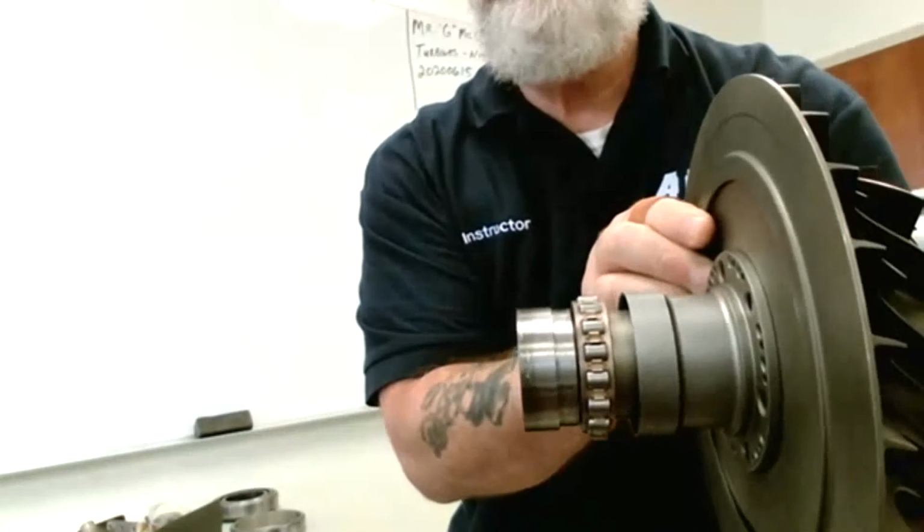The two main types of bearings that are used in the turbine engine are ball bearings, which are used for axial loads or thrust loads, or roller bearings, which are used for radial loads or centering loads, right? Here's an example of a roller bearing, right? And then I don't have a ball bearing handy, but ball bearing and roller bearing, all right? And then I don't have something to show you right now, but it's in the study material.